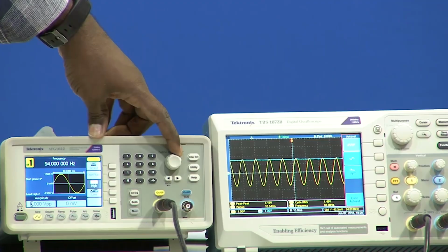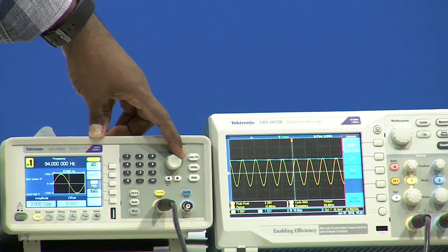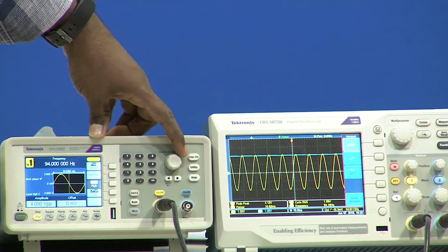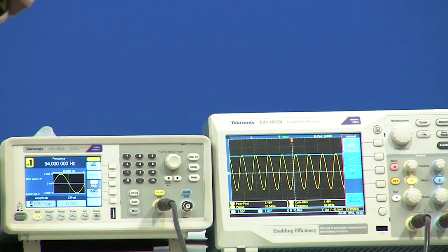Whereas when I am decreasing it, we can observe that the capacitor is slowly discharging, but when I am increasing it, we can see a quick, rapid change of going to the peak value. So that means we can understand that with this circuit we can easily find out the peak value of the input signal, right. So the peak detection part is done.